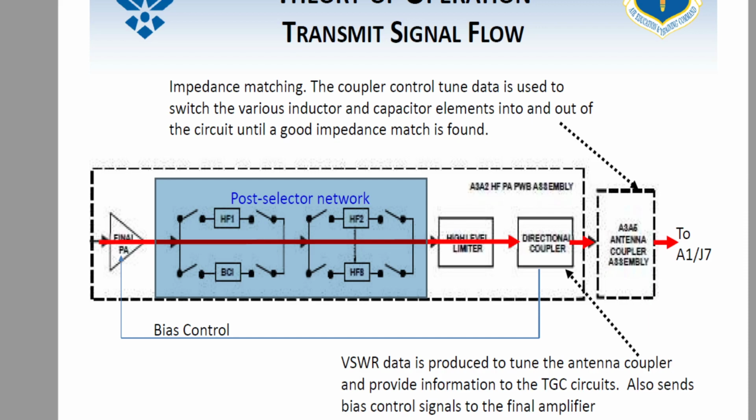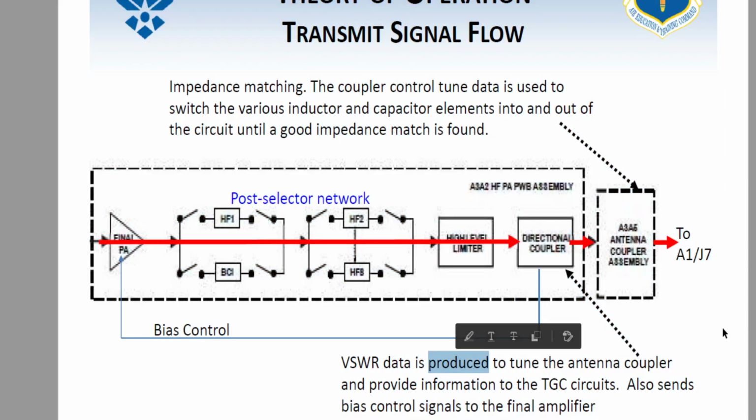Yeah, you might break them. They might pop. You might see some magic smoke, is what we refer to it as in maintenance or in RF and communications in general. That's like the blue smoke you talk about all the time, or an electronics burning smell. Usually it means you broke something or your VSWR is probably too high.